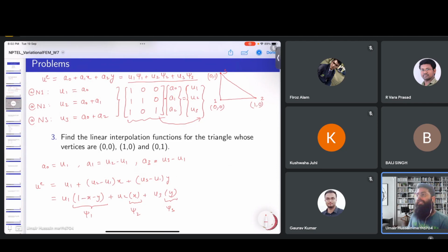That is why, when we're choosing the elements for FEM in 2D, there are certain restrictions on the elements. For example, you can't have a very thin element like this. Since its area is very close to zero, the matrix found by this element would have a determinant very close to zero. So it would be very difficult taking its inverse. In your computer program, it will give some convergence issues when you're taking its inverse.